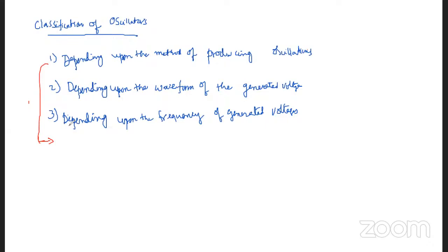In a feedback oscillator, a portion of the output voltage is fed back into the circuit in proper phase. Generally positive feedback, such that it is equal to the original input signal of the amplifier. The amplifier then provides its own input and becomes an oscillator.